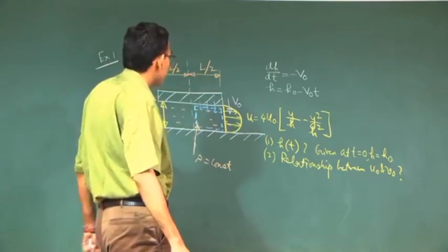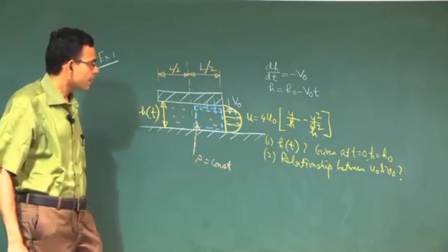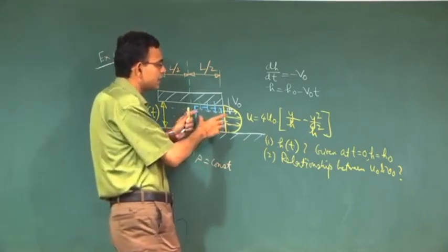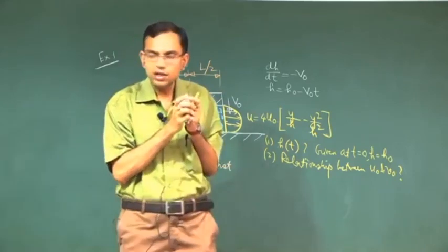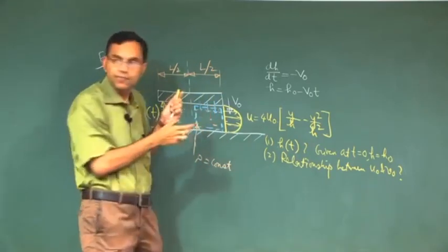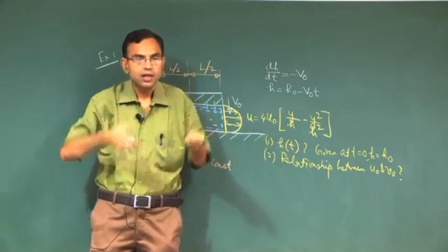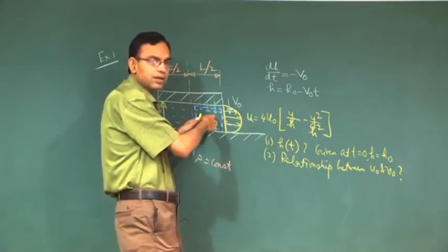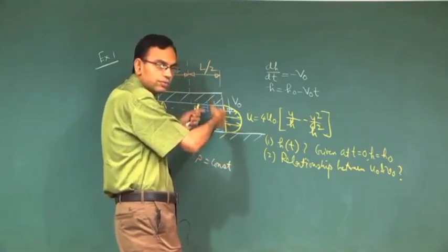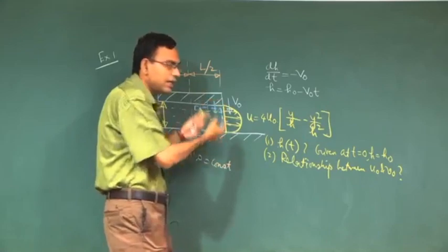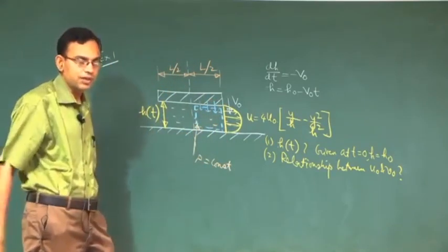So we will consider the two possible scenarios. One is a control volume like this which is fixed, another is a control volume which is moving with the plate. Drawing wise they will not look different, because you cannot draw a moving control volume dynamically in a static picture, but we have to imagine the two cases differently.